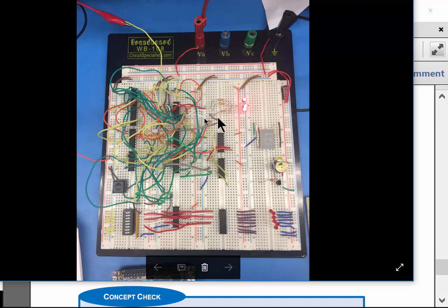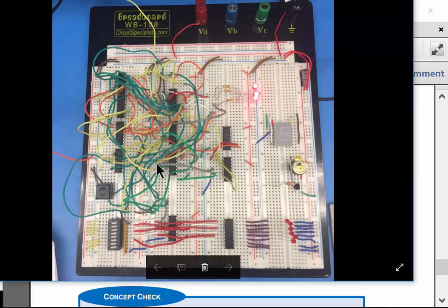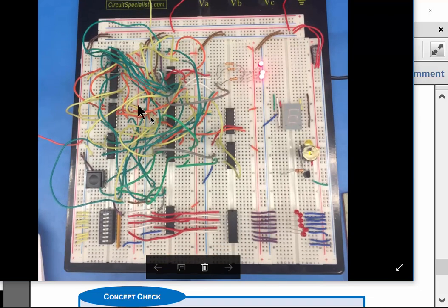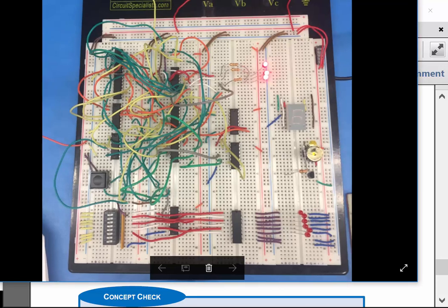You're also going to be faced with a challenge where you might not have the gates you need. You might not have a 4-input OR gate, so you might have to use De Morgan's to flip these around and only use NAND gates, because you have a lot more NAND gates in your circuit. But this is going to be a good exercise to get practice building circuits.